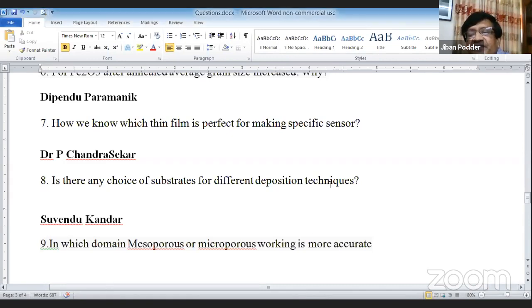Definitely there is a good adhesion between the agglomerated nanoparticles and the substrate, whether it is FTO or ITO, indium tin oxide. Especially for the spray pyrolysis deposition technique, all the films I have shown were deposited on plain glass substrate, so we did not use FTO. FTO or ITO is used for contact or for the preparation of a solar cell, with a P-type or N-type layer on the bottom.